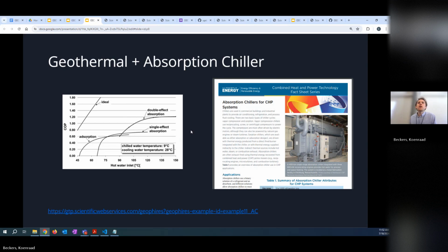There is a lot of material in the public domain. There's a lot of research, a lot of available material out there on costs, on efficiency, etc. for absorption chillers. We try to have the capability to simulate it, but we're not simulating a detailed absorption chiller. It's a similar approach as with the power plants or the heat pump. We have a cost correlation for it, an O&M correlation for it, and a performance correlation for it, like a COP. In this case, I manually provide it, but if I didn't, it would use this one, and you'll find some material out there.